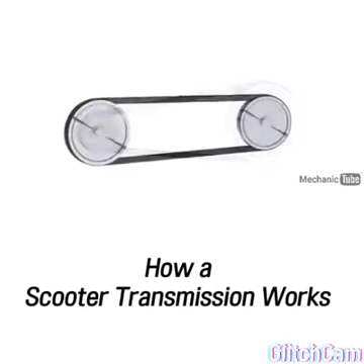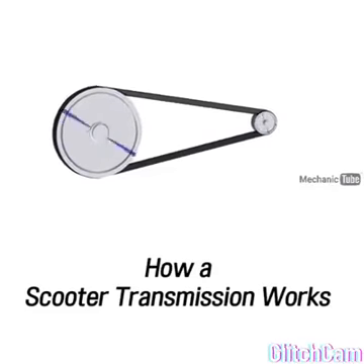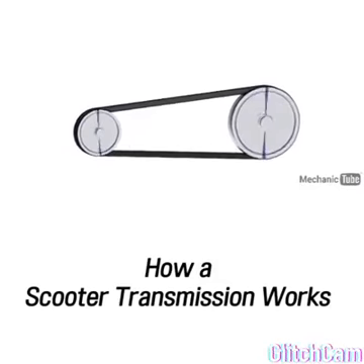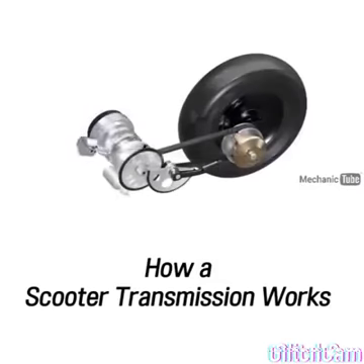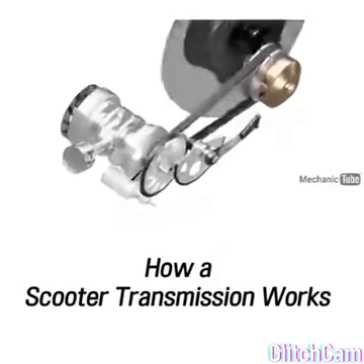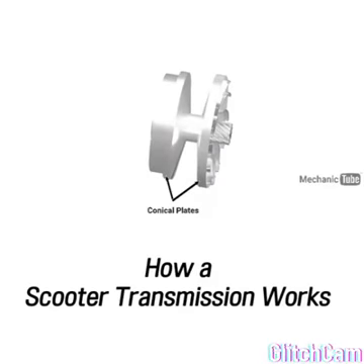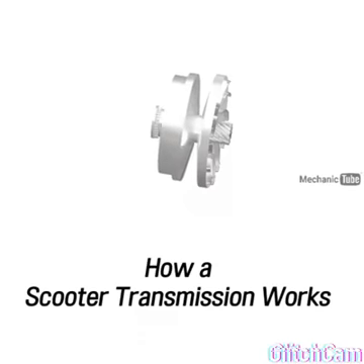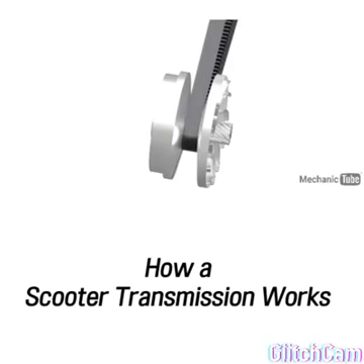It is not possible to simply change the diameters of solid pulleys as shown in this demonstration, so engineers developed certain mechanisms to obtain similar mechanical characteristics. A variator assembly is used for this purpose. Here, the pulley is made up of two conical plates. One of them is fixed to the input shaft, and the other is free to slide along its axis. A V-belt runs between these plates.